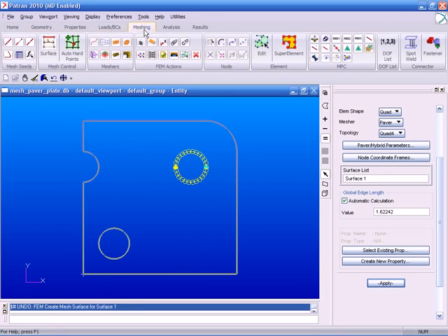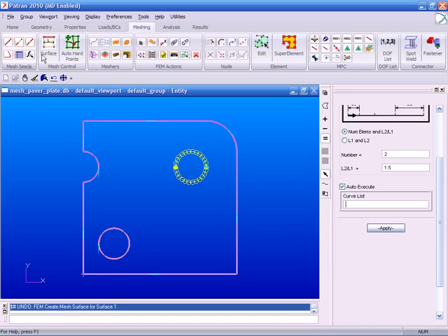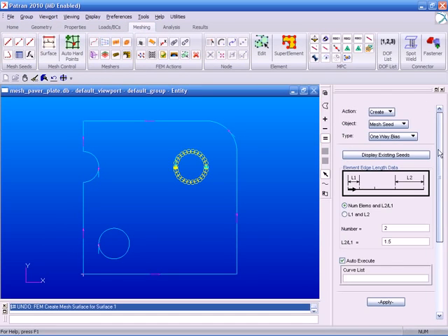Other options that I have as far as meshing and creating a mesh seed are to have the spacing be non-uniform. So with a one-way biased mesh seed, say I want to create, in this case, 20 elements with a ratio of 3 to 1 for the longer spacing to the smaller spacing. And I'll do this along this left edge of the plate. I can see that I'll have much finer, or somewhat finer element spacing down here as opposed to up here.